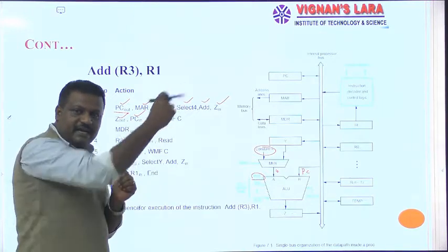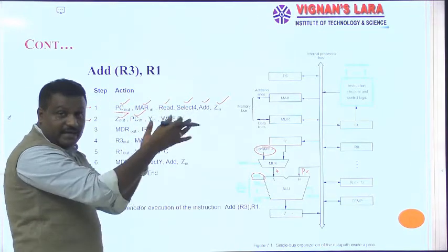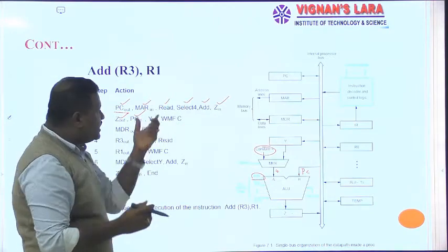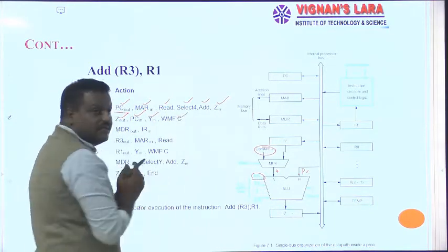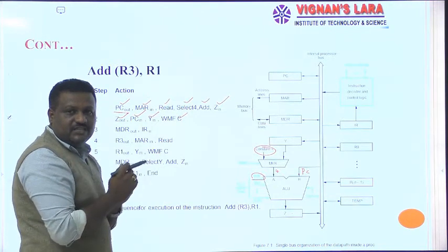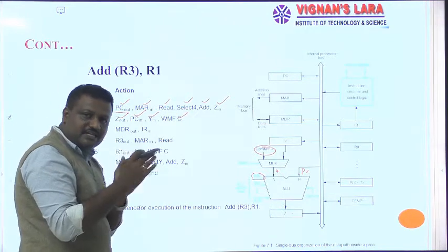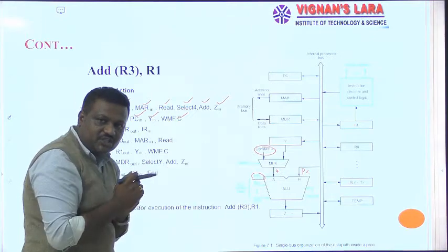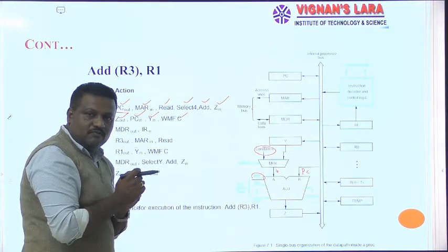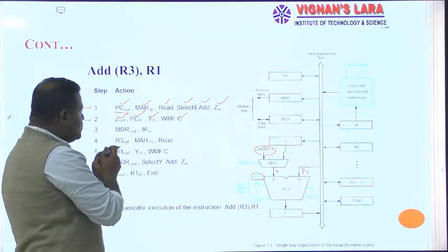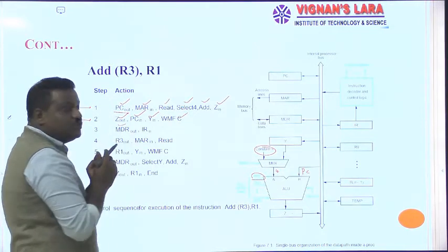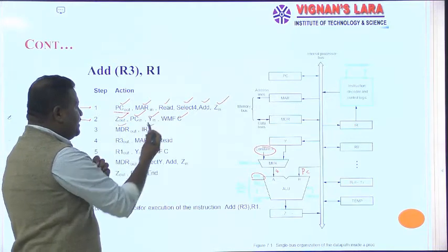In the meanwhile, I receive something from external memory. So the data was copied onto Y in. I activated a control signal, that is the memory wait signal. That means I wait for a certain amount of time to read data from a memory location. Once my data was placed onto the data bus, I'll go and catch it. So in this case, MDR out, then IR in.